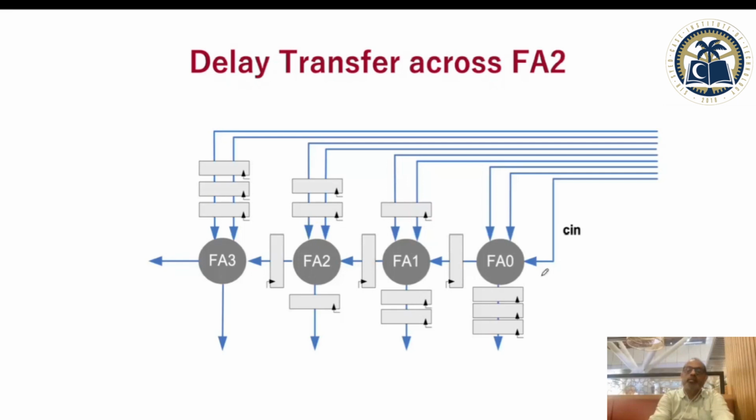And now, systematically, what you have done is that the number of pipeline registers that you want to take into your cloud, you insert them at the input, and then systematically you keep leaving a register where it has to be left. Moving forward, another register, another register, and if you do this systematically, your entire design will be able to run at a very, very fast clock rate and will be synchronized. So you don't really have to worry about what your paths are and how to figure them out if you want to deeply pipeline a design.